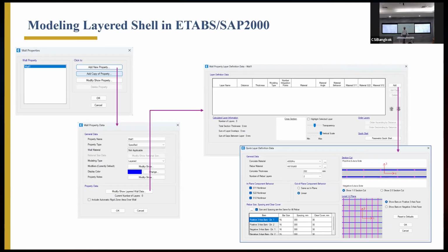So you can model very complex behavior both for slabs and for walls. And this behavior, what is called isotropic and orthotropic behavior, can also be modeled. So this can also be used for one-way behavior, deep beams, many applications. So it's a very powerful element that you can use to do full nonlinearity, which is distributed.